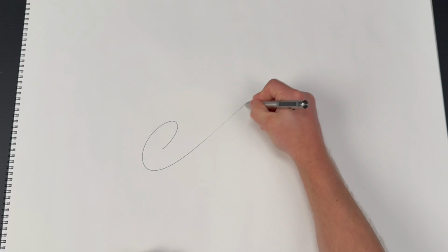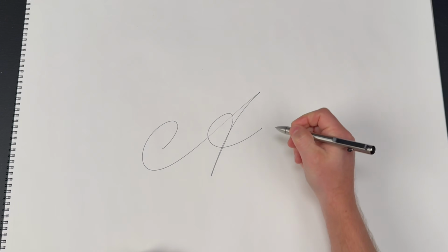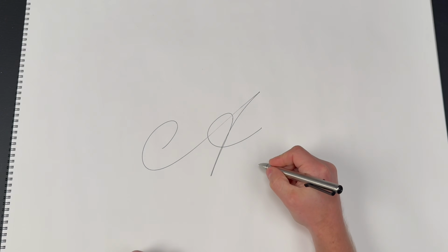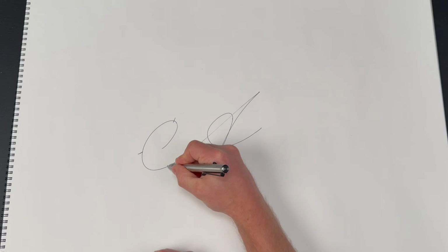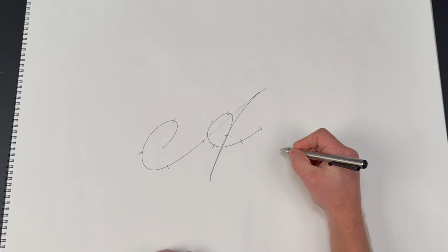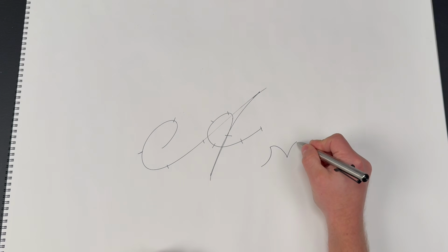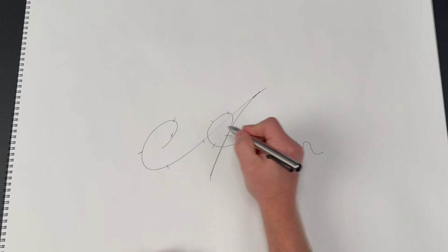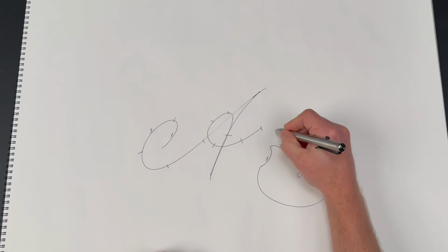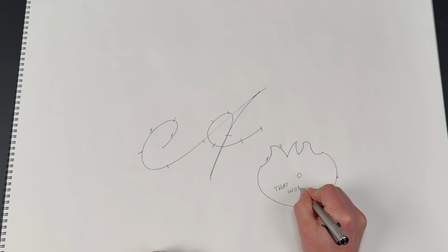Think of the problem of how to use a cam to create a complex motion, such as that of moving a pen to write the letter A. You can break the profile of a cursive letter A down as follows, but you can't just cut those curves into a metal cam and attach it to the arm holding the pen. The reason for this is while the pen does move, it will write on top of itself because the cam can only push or pull in its place.